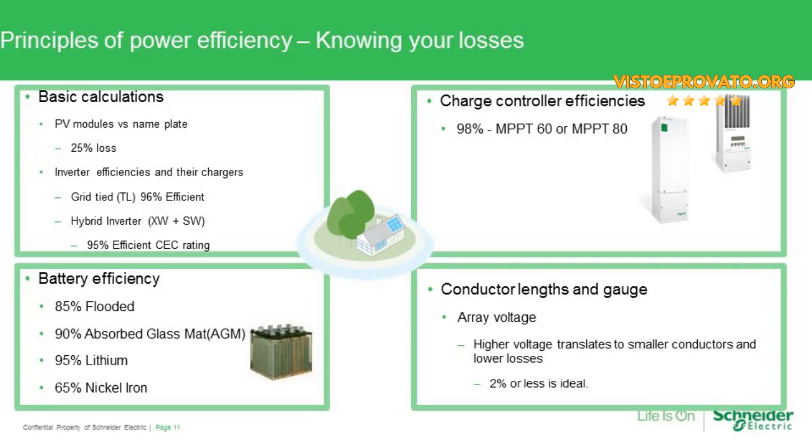Beyond that, of course, we have to understand that the inverter consumes a little bit of power on its own during that conversion process from stored DC energy to AC. So that definitely needs to be taken into account when doing the calculations. If, for example, you're trying to do an AC coupled system and understanding where that power is going during the daytime versus the nighttime, we'll jump a little bit into that, but it could be that 98% efficiency of the grid tie inverter is the number that you would end up looking at if primary consumption is during that time. Of course, battery efficiency, if it's a straight backup system,